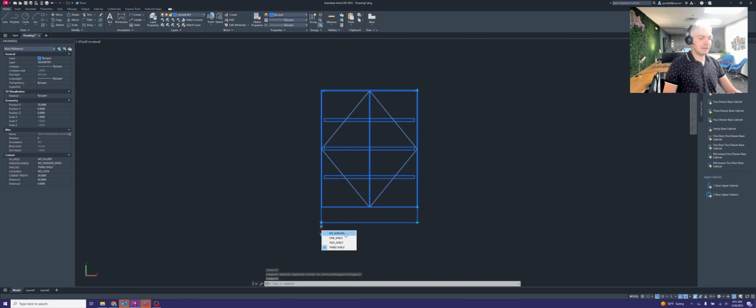Sometimes 3 shelves may not be enough though. It depends on the architect's needs. If they have a cabinet that needs more shelves, you may have to add those in custom. The block only allows you to go up to 3 because of the limitations of what we have in AutoCAD, the number of views that you can have within a block, which we'll talk about when we get into block editing later. Anyways, so you can drop down and go no shelf, 1 shelf, 2 shelf, or 3 shelves in this cabinet.